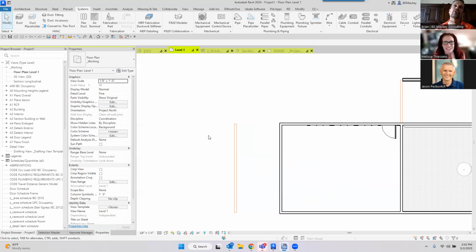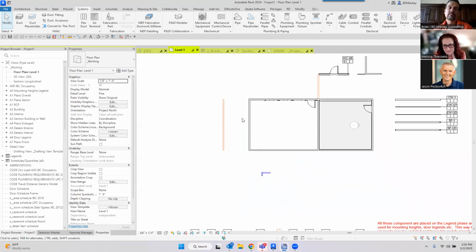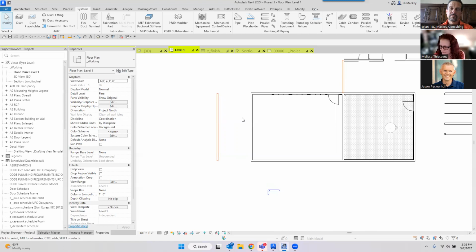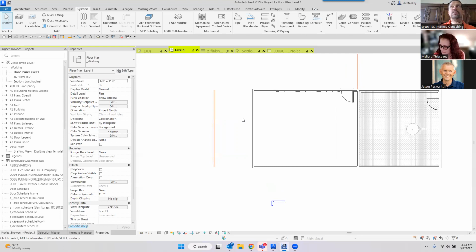No, because right now our below grade floor plan is set to be like 6 inches above the bottom level to catch the walls so we can see them. But we have to turn fixtures and furniture and all that stuff off, which we can do in the view template. But it's really not there when they're doing the grade piping. Yeah. The only thing I can think of is do like you said, cut your view range like 1 inch above the floor or whatever, and then have a filter create all those walls to be dashed or whatever line style you want.